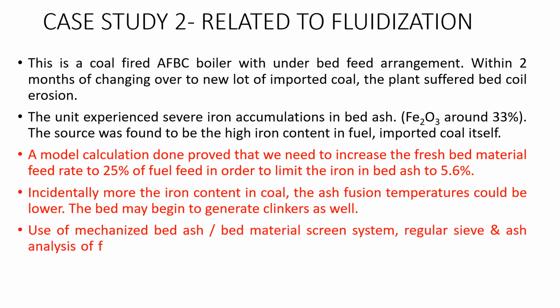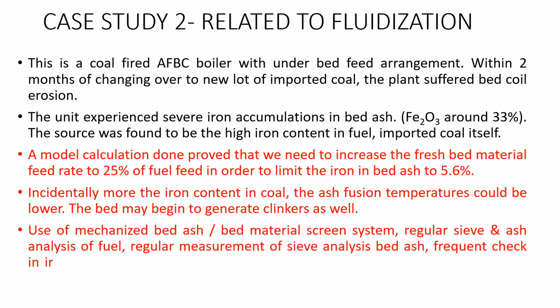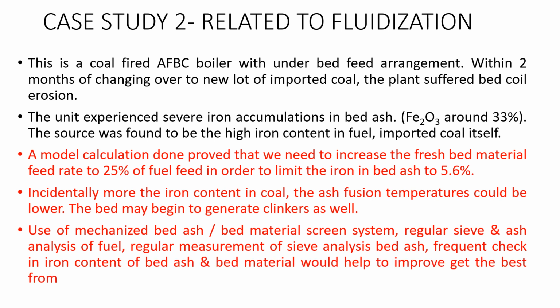So use of a mechanized bed material screening system, regular sieve and ash analysis of fuel, regular measurement of sieve analysis of bed ash, and frequent checks of the iron content of bed ash and bed material would help to improve and get the best from these AFBC boilers.